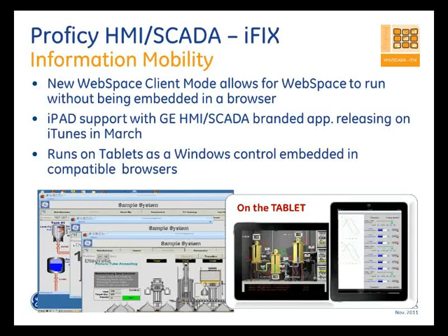When you go to iTunes and search for Prophecy SCADA, it will come up with an app that you can download on your iPad and connect to the WebSpace server. The app is at no cost on iTunes. It basically consumes a CAL that you will have on the WebSpace server. So again, since WebSpace works in a concurrent licensing environment, if you use that CAL to run an iPad client, obviously you'll have one less client that you will be running somewhere else. But that's more of how you manage your concurrent client connections. So that's one important aspect of WebSpace with 5.5.